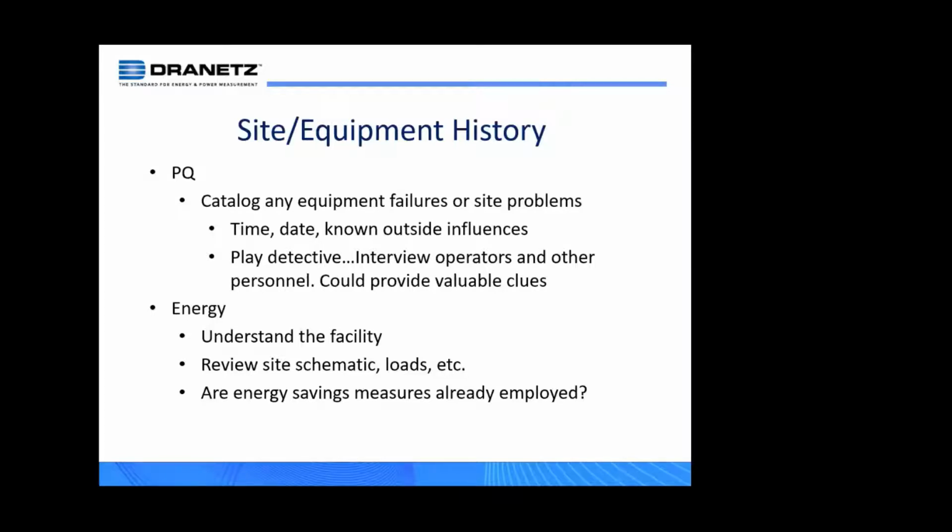Okay. For energy, it's a lot about understanding the facility, reviewing the schematic, the load types, things of that nature. Are there energy saving devices already employed? So a lot of times it's more than just simply running out to a site and putting a power monitor on a circuit and collecting data. As you can see, the point here is there's a lot of preparation that you do before you even install the monitor that will help you be more efficient down the line when you're analyzing this data and making decisions as far as how to mitigate or how to save energy.